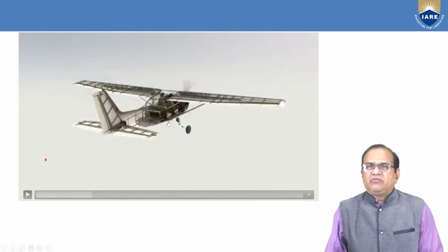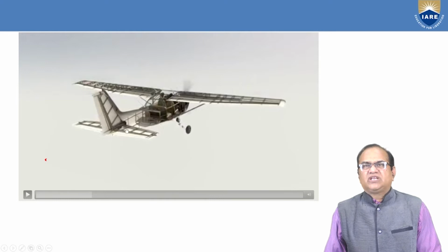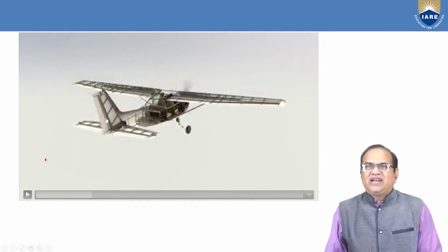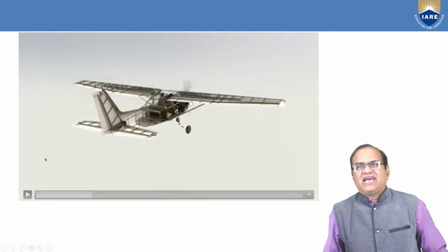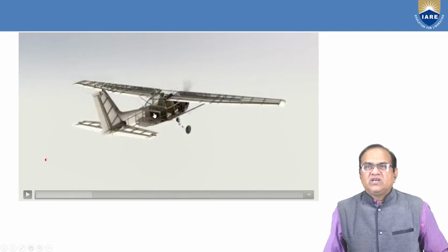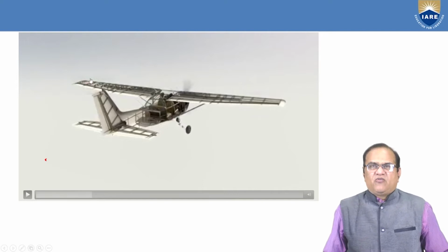And here, in this horizontal tail also we have airfoils 1, 2, 3, 4, and small longerons here. Here also are the vertical longerons for the vertical fin, divided in a number of parts, and above that the skin is fixed. So you can see this fuselage. The fuselage is a skin, monocoque, semi-monocoque structure. Wings are made of longerons, stringers, then a number of airfoils, and it is covered with a skin.